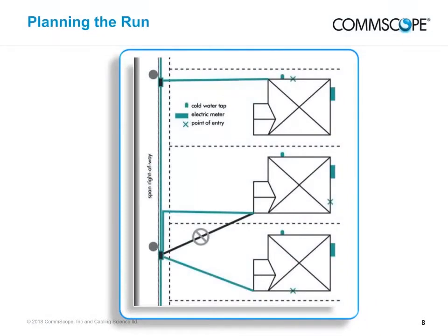The time you take in examining the site prior to installation is well spent and can help you avoid problems later on. You need to be aware of issues such as right-of-way, or ROW, where you will tap into the span, the distance of the run, and where you will attach and bond the cable at the customer's structure.